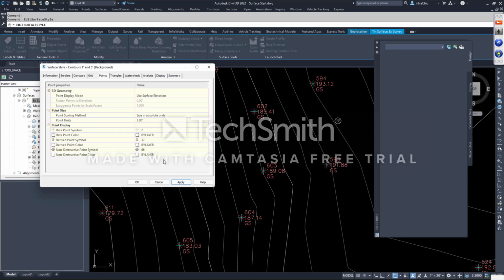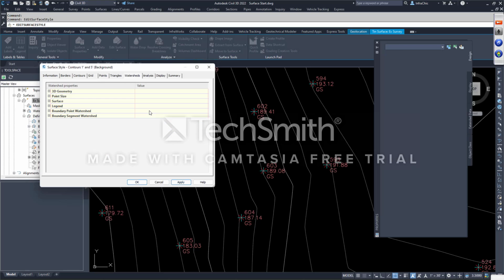If I go like that, I don't think there's any out there. I'm not seeing any change. We'll see it when I leave these on. If we run into a circle and a dot, you'll know that's a derived point. Triangles, that's the TIN you saw earlier. Watersheds, I showed you that really quickly. That has its own legend, its own surface, its own point sizes. It has a bunch of different drains and how those are handled. The analysis tab deals with the others: the slope arrows, the slopes, directions, and whatnot.